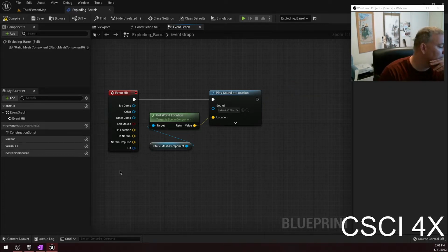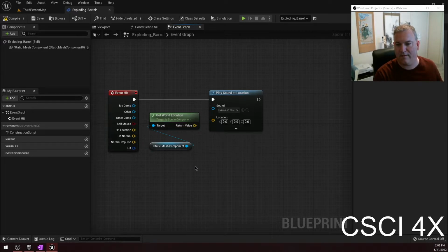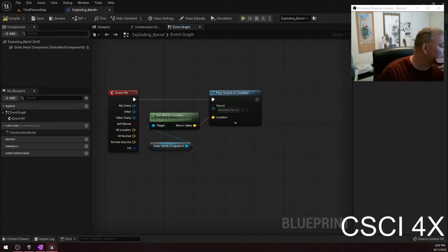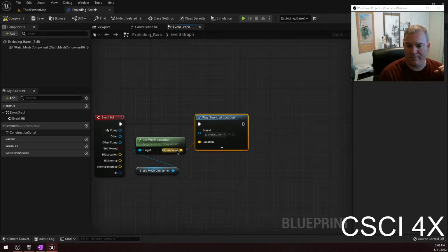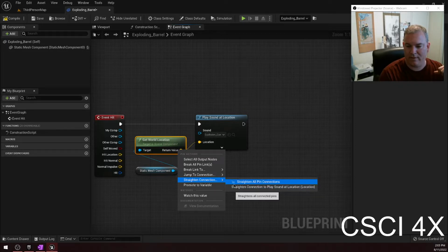Okay, Alt and click the string. Yeah, just like that, and then it cuts the connection, cuts the cord. All right. Okay. Right click and choose which connections to break. Correct. Yeah, you can right click and choose break all, or you can break a specific one. You can also right click and follow it.